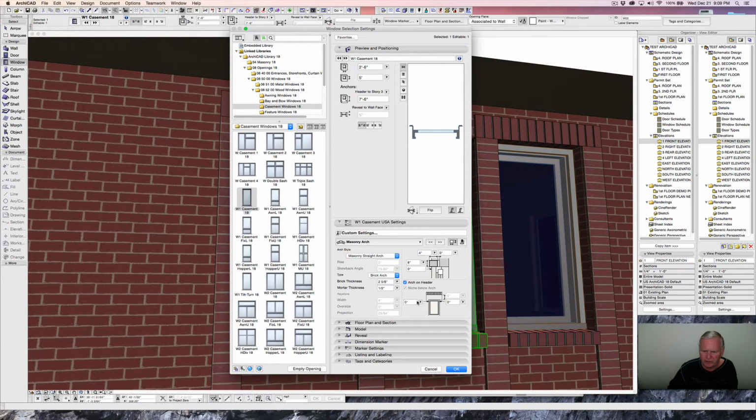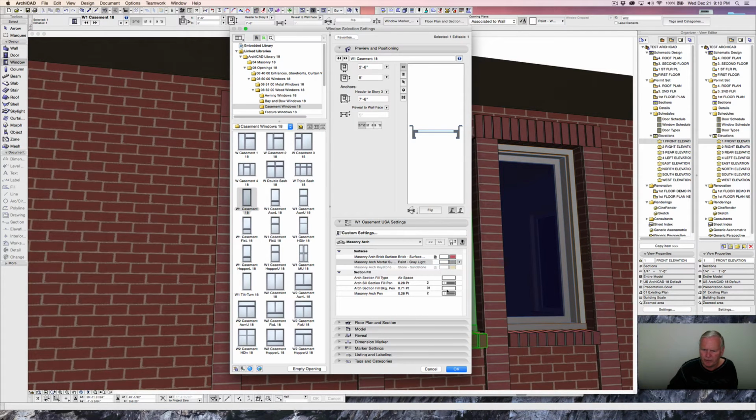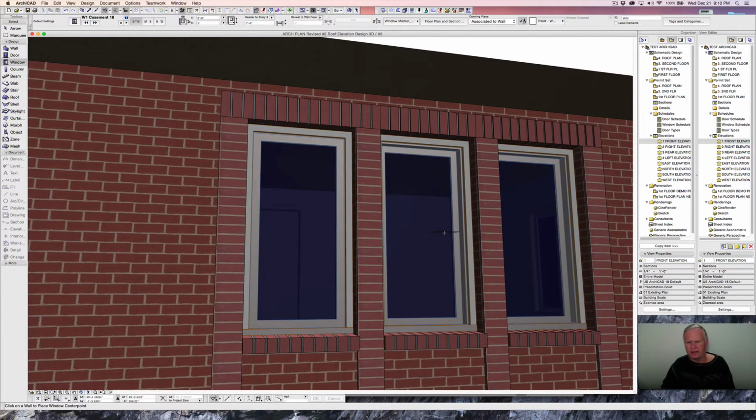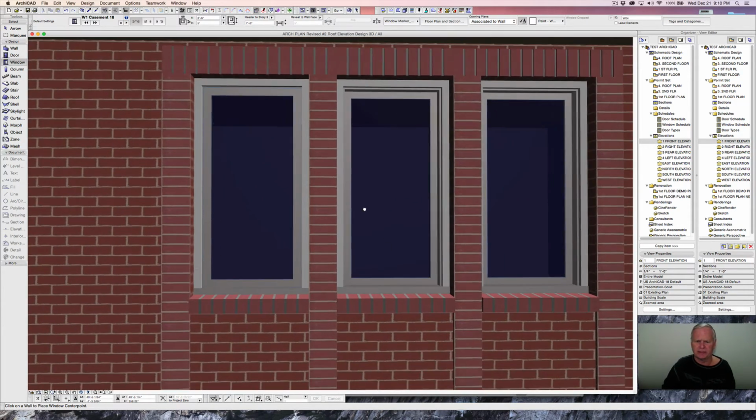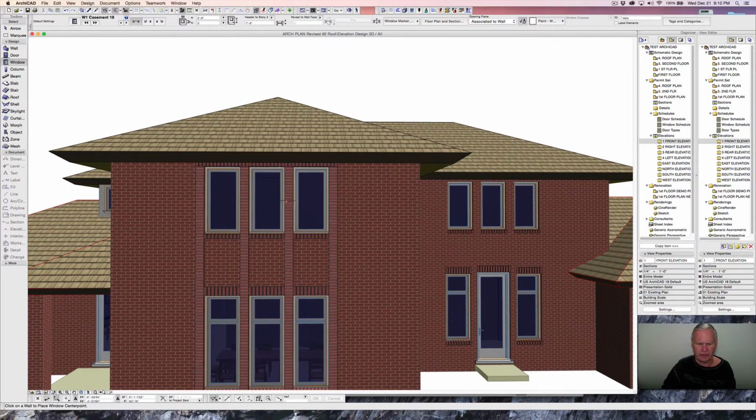And then we're going to leave these overhangs alone and just get this 7.625 set in correctly, and this 3.625 correctly, and the 1-inch overhang, and switch here to our colors and do surface color and do the light gray and do our pen. Click OK, and there we go, and that looks pretty good. So that worked out pretty nicely.